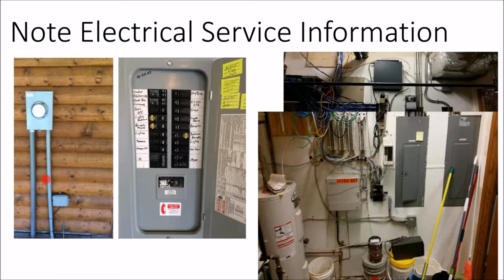And so during the install, we'll get the utility out to come pull the meter, and then we will pull some of the conductor out through this cable, cut into this conduit here, put in a box, pull the conductors back through into the meter can, and then tap on to the conductors inside this box. So this picture, you want to learn everything about the electrical service you can, where the power enters the property, where it enters the building. All of this data is very useful. Where is your wall mounted stuff around your utility going to go?